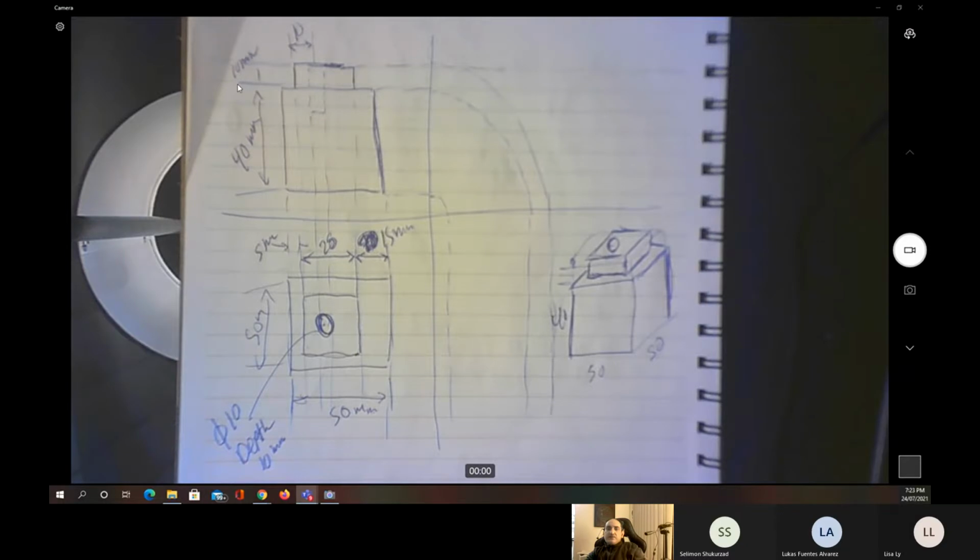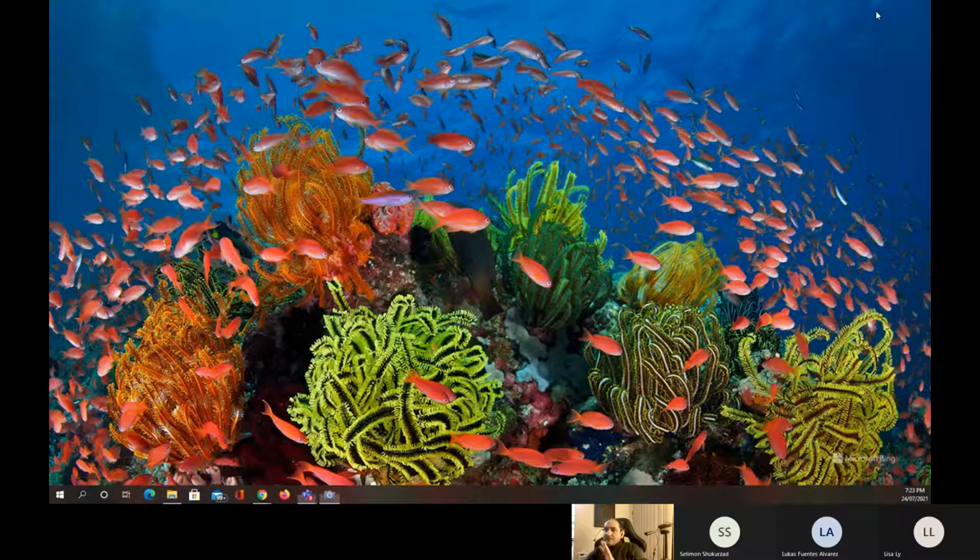So we have to do it, let's say, 3 millimeters each time by rough cutting, and then the last cut of 1 millimeter layer is going to be removed by what we call the finish cutting. And when we finish with that, we are going to do the drilling for it. So just a simple code. Everyone can write it down, and then we are going to upload it and put it in any simulator.